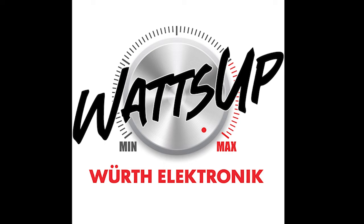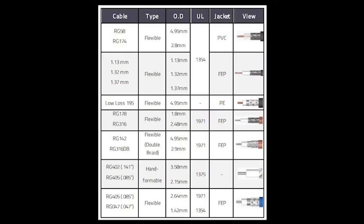Different standard materials used for each of these parts include a solid or a standard Cu center conductor, PTFE or FEP dielectric, a single or a double layered shielding or braid, and a jacket typically made of PVC, PE, or FEP.